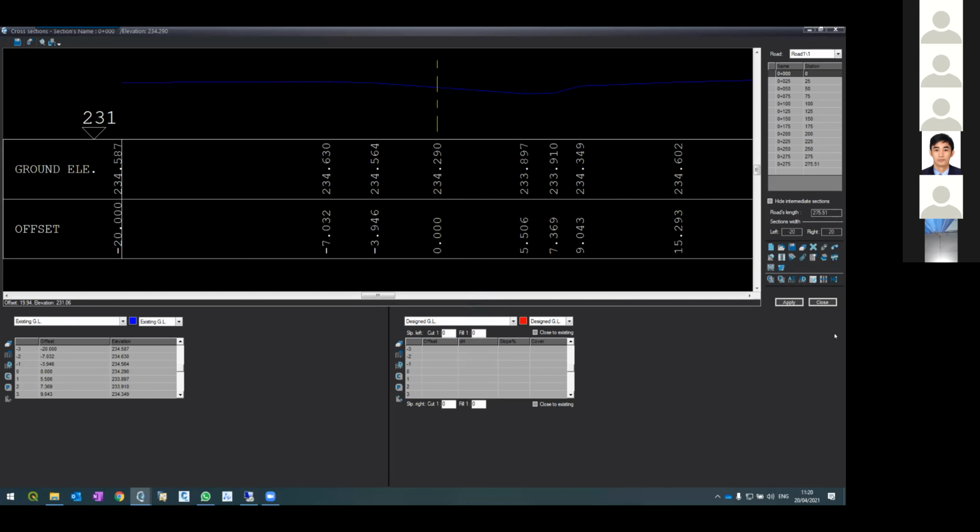The next thing that I'm going to do is design my road. So again, please, everybody pay close attention. I design my road using the first section, section number 0. This is where I start designing my road. How do I do it? I'm going to the lower left table. I don't need this table anymore. So I change it from here to structure. Structure is the top level of the road. What we call crown point is the center of the road.